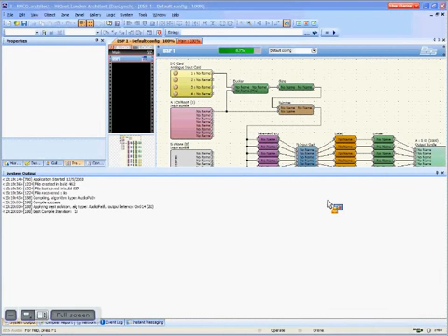What percent utilization was it? And then it'll compile your objects 5, 6, 7, 8, 1, 2, 3, 4. Okay? Then it'll compile your objects 1, 3, 5, 7, 4, 6, 8. And then it'll compile your objects in some other order, and another. It goes through all these combinations until it gets to a point where it's obviously just not getting any better. In some cases, it's getting quite a bit worse. But at that point, it knows with a high degree of certainty what's the best way to compile these processing objects to use the least amount of DSP power. Then it goes back and it recompiles them that way.